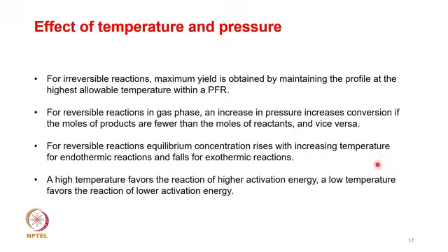In a reversible reaction, the equilibrium conversion rises with increasing temperature for an endothermic reaction and falls for an exothermic reaction. So pressure and temperature act as key variables in terms of the driving force of the reactions. And typically a high temperature favors the reaction of high activation energy, and low temperature favors the reaction of lower activation energy. So in addition to whatever we have mentioned, which is based just on the geometry, the hidden factors which may play a role could be the effect of temperature and pressure.